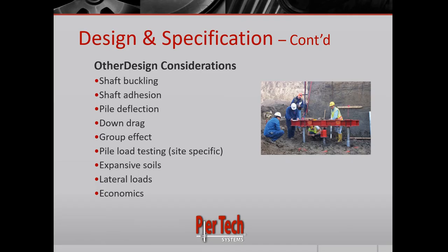A fluid soil would be one that has a blow count value of 0, meaning that when they set the hammer on that soil, it drops the 12 inches without any effort. It can't even support the weight of that 130-pound hammer. So that would be considered a fluid soil.